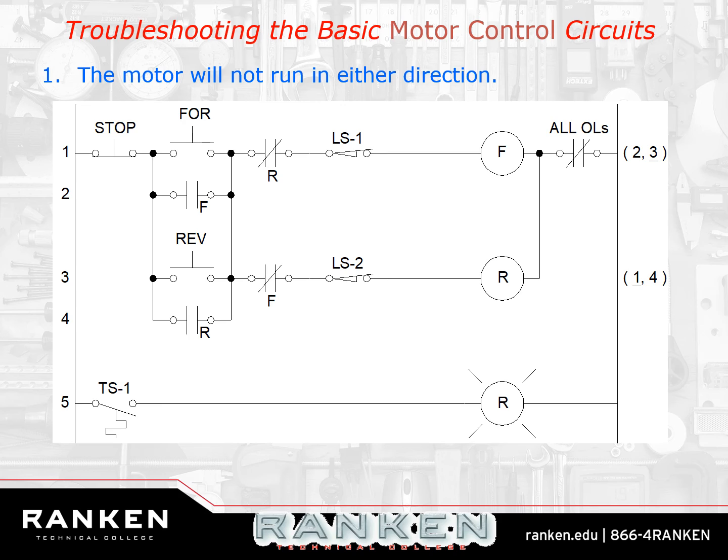And it'd be really easy to check, right? Because from here to here, if I push that forward button or the reverse button, I should get source voltage. If I go from here to here and I push the button, I should still get source voltage. If I don't, that's open.